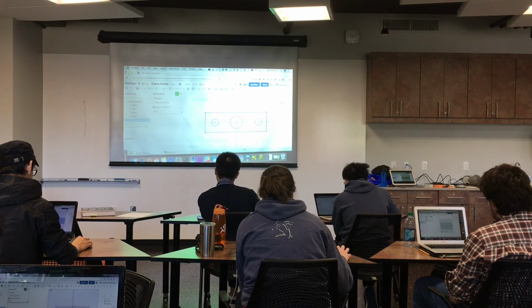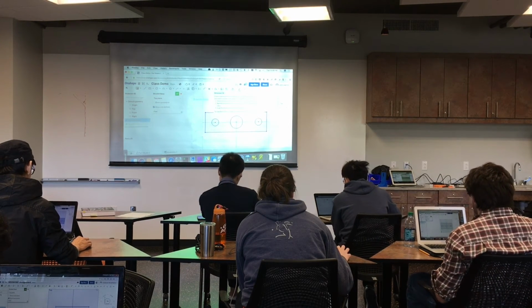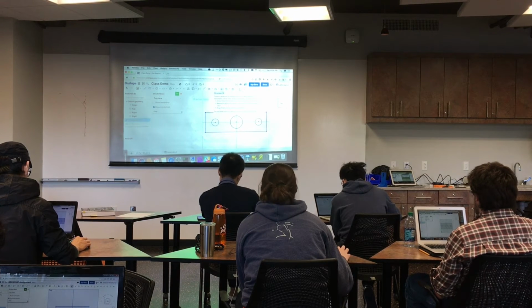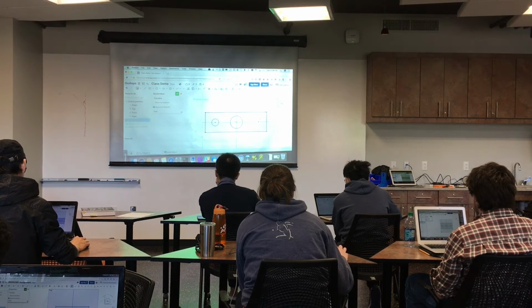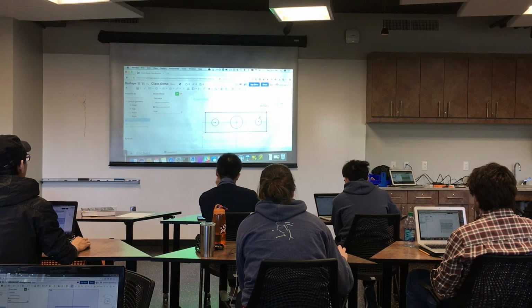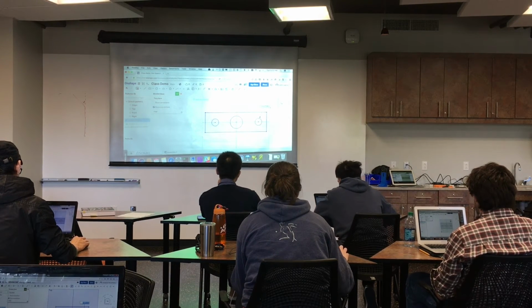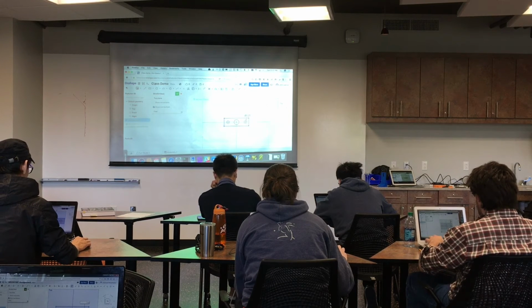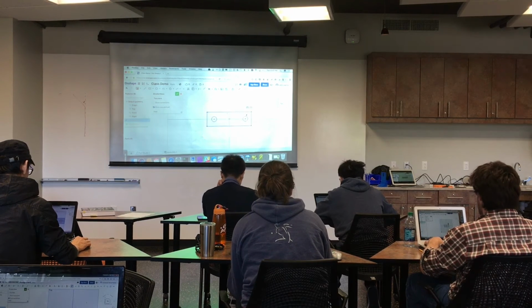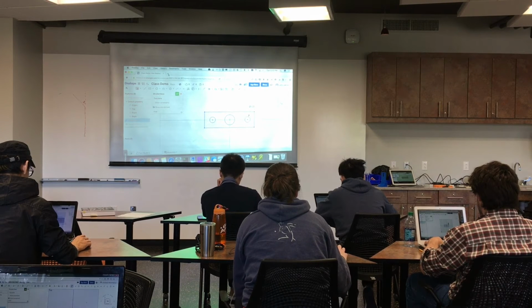And now we need to tell this what dimension we want those to be. So this is your dimensioning tool, the two ticks with the arrow. Go ahead and click that, and click on one of these, your favorite one, left or right circle. When you do, you'll get this diameter callout. Click, and now enter the size that you want it to be. For now, let's say 1/4 of an inch, 0.25, and enter. Now, we have 1/4 of an inch piece of rod coming through in reality.